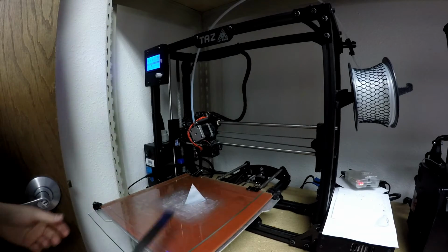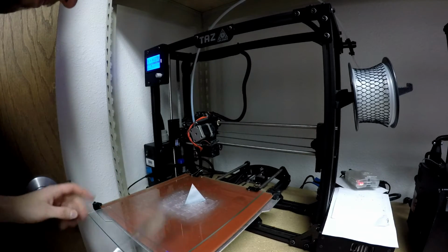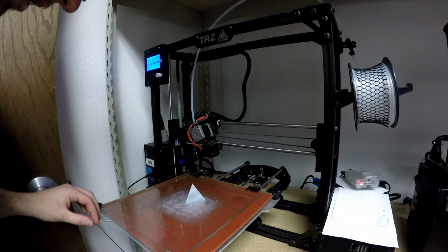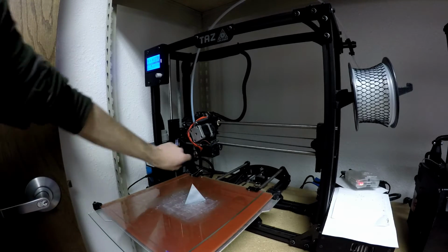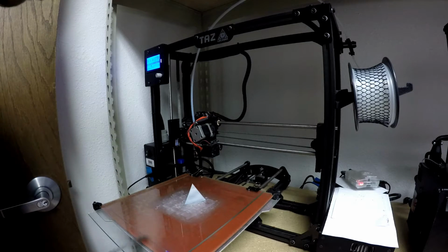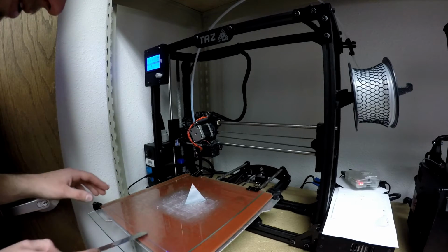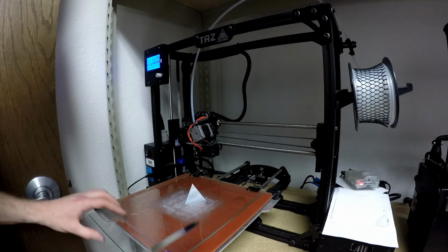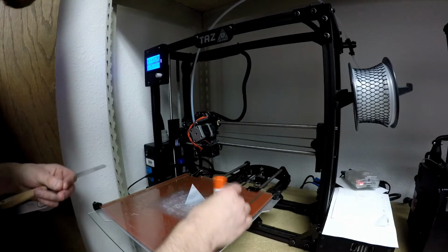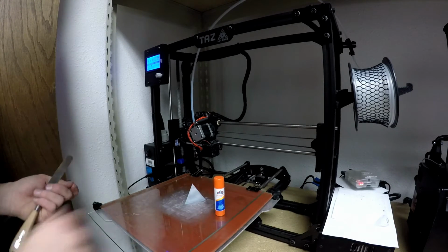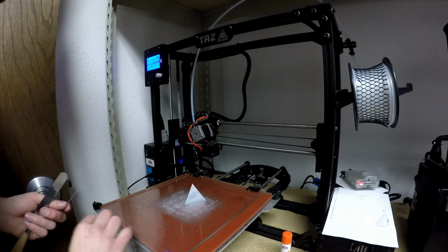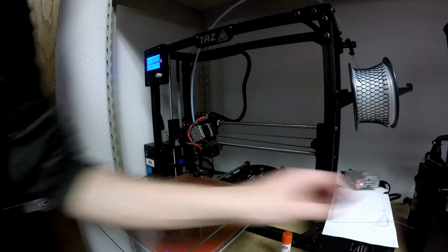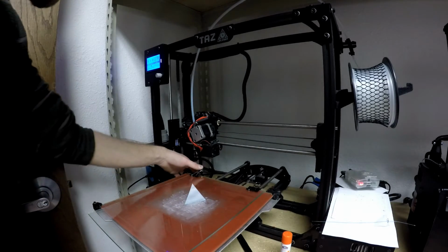So for those of you that haven't seen this awesome mod you can do to a Lulzbot, you basically can just buy a sheet of glass, get some binder clips, and then print out this little spacer, and you can print nylon super easily. Because with nylon, you need to be able to print on a glue stick. So that's why in the beginning of the time lapse you saw me put down this Elmer's glue. That's just to help the nylon stick to the glass. It's kind of a cool thing that Taulman puts into their filaments.